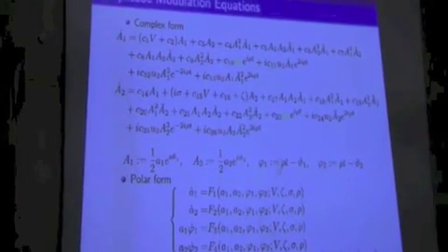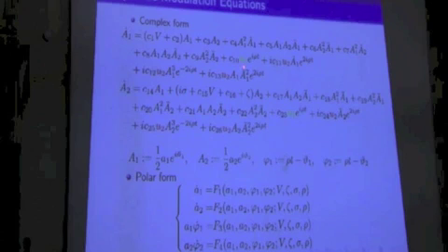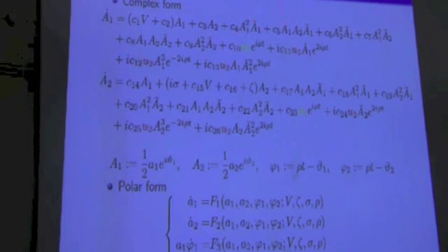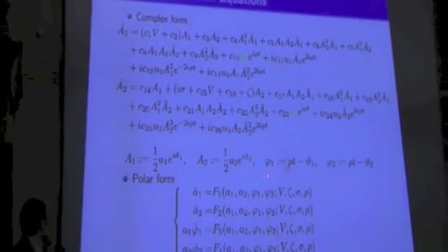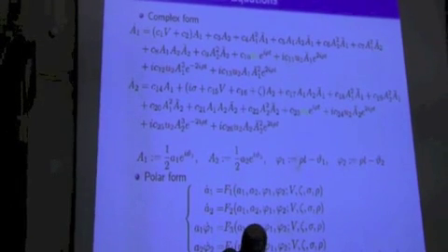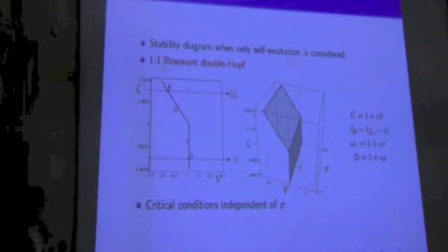And these equations in particular are the normal form for the one-to-one internal resonance double Hopf bifurcation with some perturbation terms due to the turbulence here, the green and the red terms. So we can go to the real equations, which are four here, introducing a polar transformation. In particular, A1 and A2 are the two real amplitudes of oscillations of the two towers, while phi1 and phi2 are the phase differences. So we can consider the solution here of the problem.